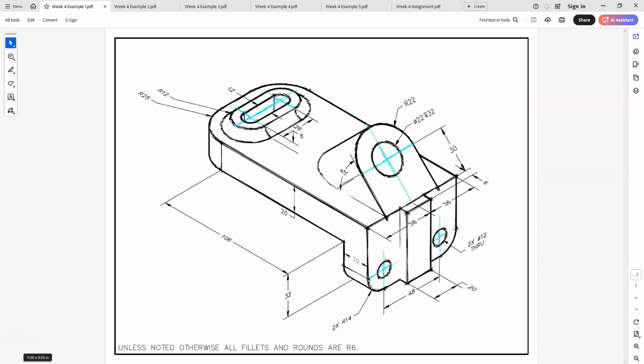here using Solidworks. Now before we get started, we're going to see that we have to make some references in here. Mainly that we're going to have to create some kind of plane in order to be able to get to this shape here. There is no other way that I can think of that I would have to create that without having some kind of reference. And what I mean by reference in the term of SolidWorks, it means something like an axis, a point, or a plane. And in this case, we're going to be using a plane. So I'll show you how to create a plane in SolidWorks. So let's go ahead and jump over to that and get started.